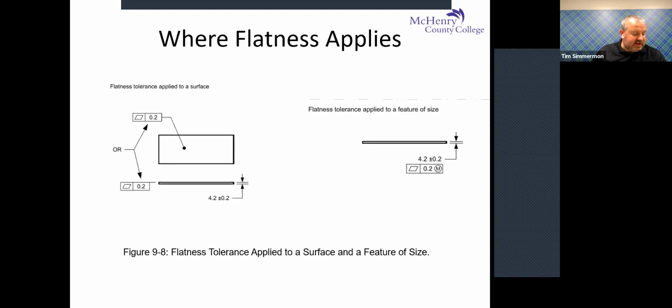So that flatness and that length tolerance both apply to that feature of the part, but they're located separately on the drawing. So that flatness applies across the entire surface. Yep. So if you sweep it with an indicator, it should be within tolerance, or it's not a good part. Exactly. Or with a CMM or whatever you're going to use to measure it. No, exactly. You're exactly right.